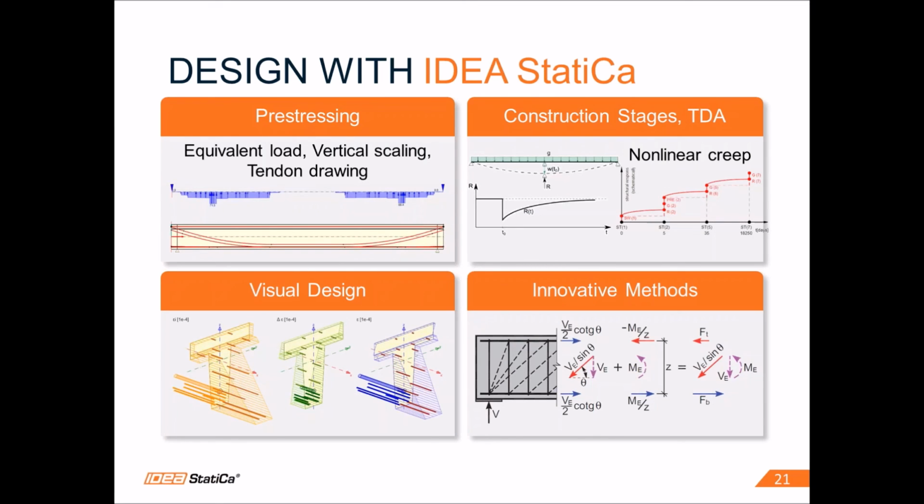You might have a question why we should export the data into IDEA StatiCa. We already tried to mention the advantages. For example, in case of prestressing, we can show equivalent load, as you can see here. We can scale the structure in vertical direction, we can produce draft tendon drawings and send it to the DXF file.